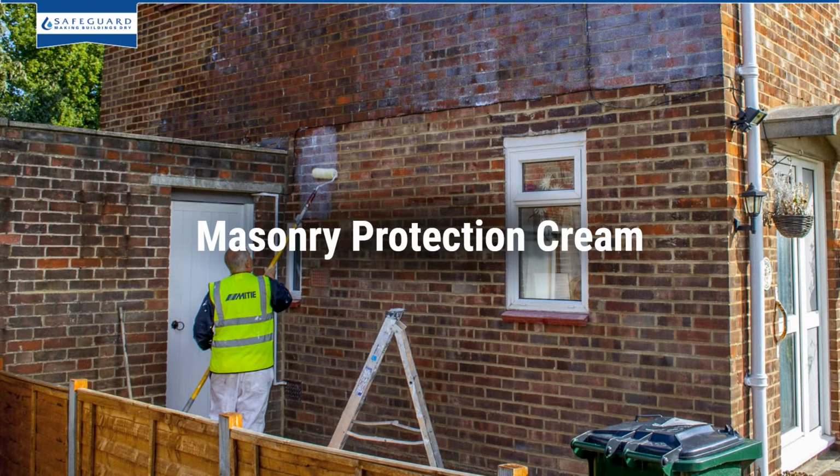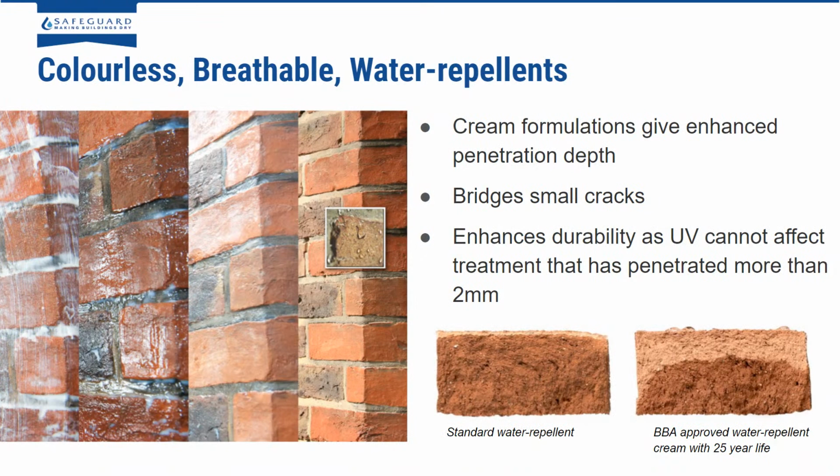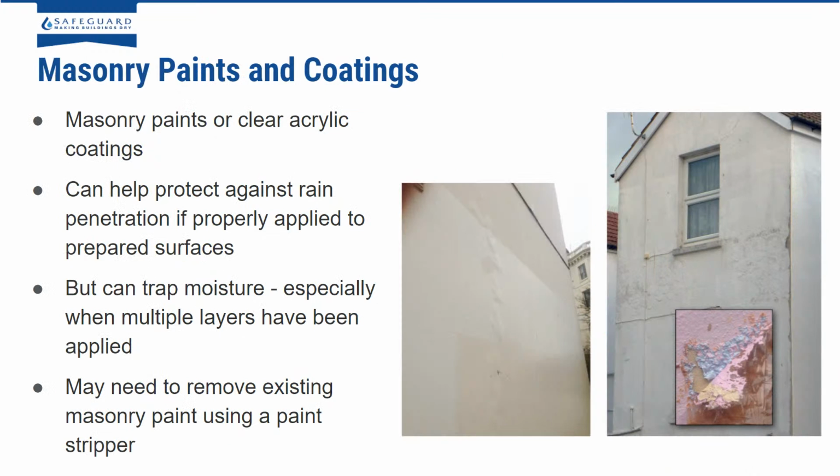So looking at masonry protection cream as one of these measures. Like I say, the cream formulations are quite great because they have a higher actives content, which has higher penetration depths. They can also bridge smaller cracks compared to liquid water repellents. And because of the enhanced durability against UV, they can last a lot longer. And because they have a higher penetration depth, it means that anything behind the surface will also stay hydrophobic. And so if there is any erosion of the brick face, you'll still have some form of waterproofing behind that as well. So yes, that's masonry water repellent.